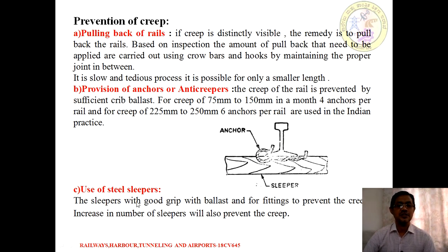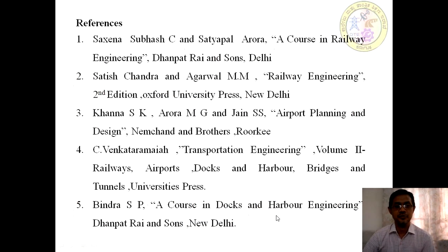Similarly, if you use steel sleepers, as they have a good grip over the ballast and the fittings, some amount of creep can be prevented. An increase in the number of sleepers also helps to prevent creep.